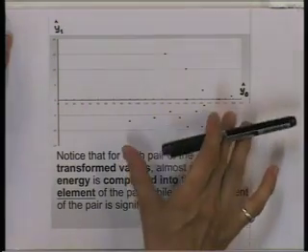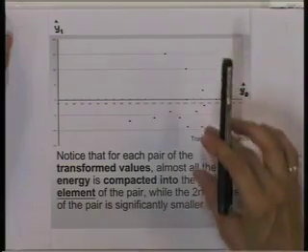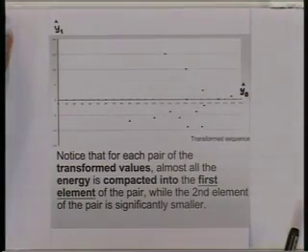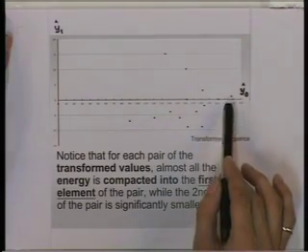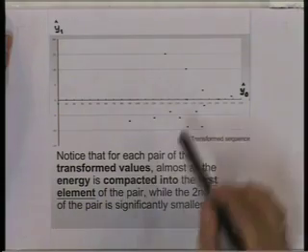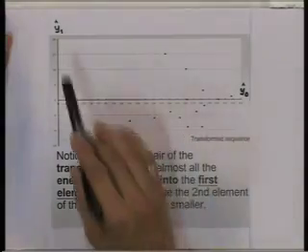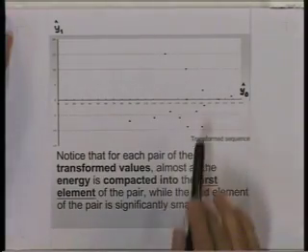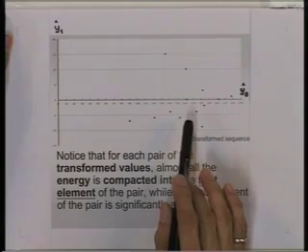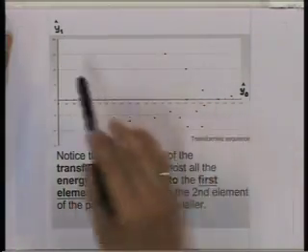The variance of y0 is much larger than the variance of y1, and therefore, as discussed earlier, the information contained in y0 is much higher than the information contained in y1. And now, since y0 and y1 are decorrelated, there is very little common information between the two components.